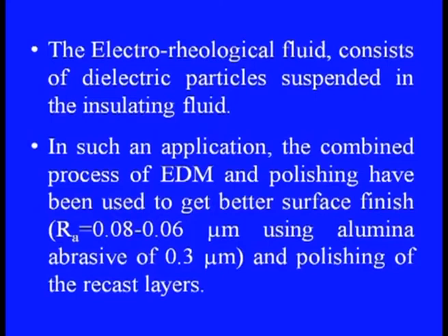The electrorheological fluid consists of dielectric particles suspended in the insulating fluid. In such an application, the combined process of EDM and polishing has been used to get better surface finish, in which average roughness is obtainable to the tune of 0.08 to 0.06 micrometer using alumina abrasives of 0.3 micrometer size, and polishing of the recast layer could be obtained.